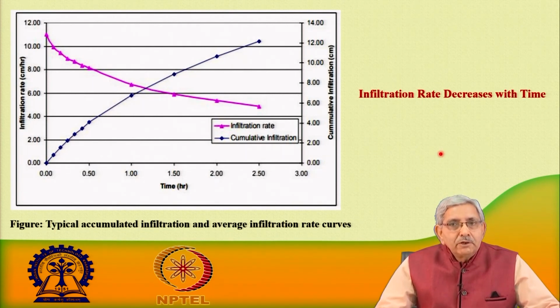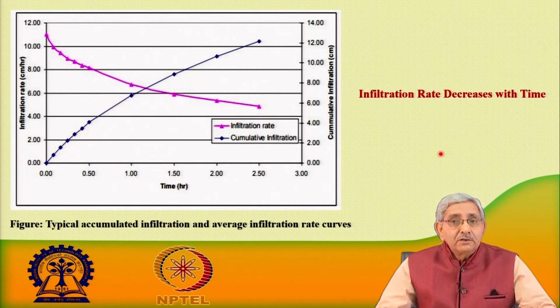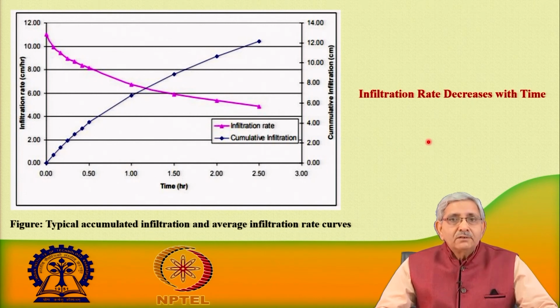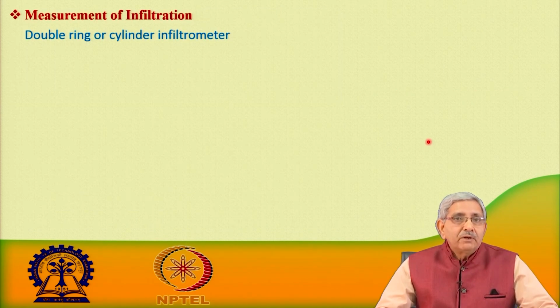Now, the infiltration rate decreases with time. What happens is that the topsoil pores become saturated and the moisture content has increased. So, that has caused a decrease in the rate of infiltration.